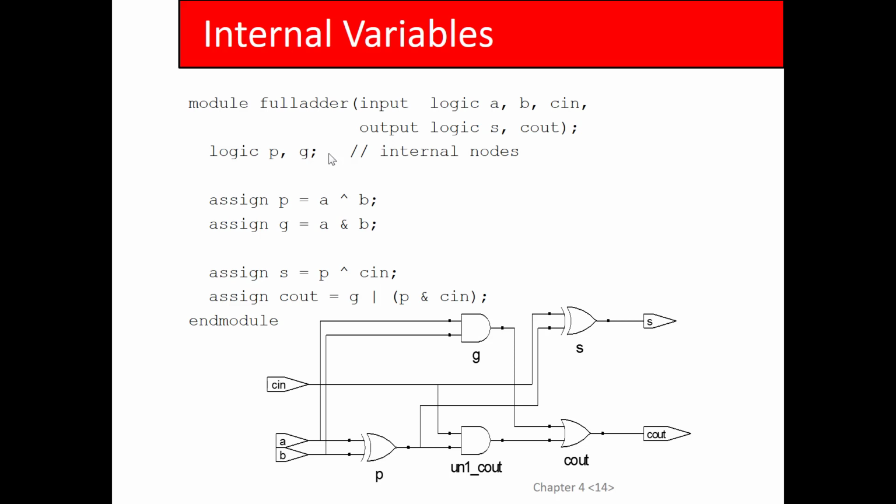But this reduces down to the same old full adder that you're familiar with. In other words, the propagate and the generate become important when you scale up to multiple bits, but if you're looking inside of one full adder, then this is equivalent to the one you've always known. So the sum is just the XOR of A, B, and C in. And then C out is generate or propagate and carry in. If we've got a propagate and a carry in, we'll pass it through as a carry out. Otherwise, if generate is set, then we're just going to generate a carry out no matter what. Now, what is the point of this?